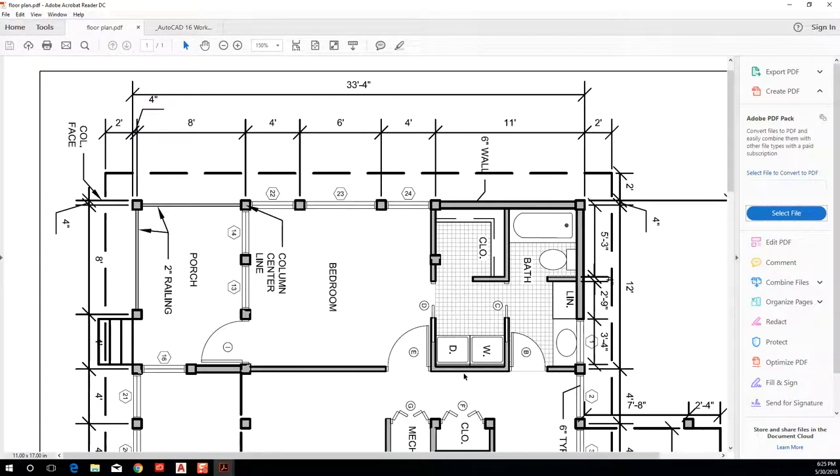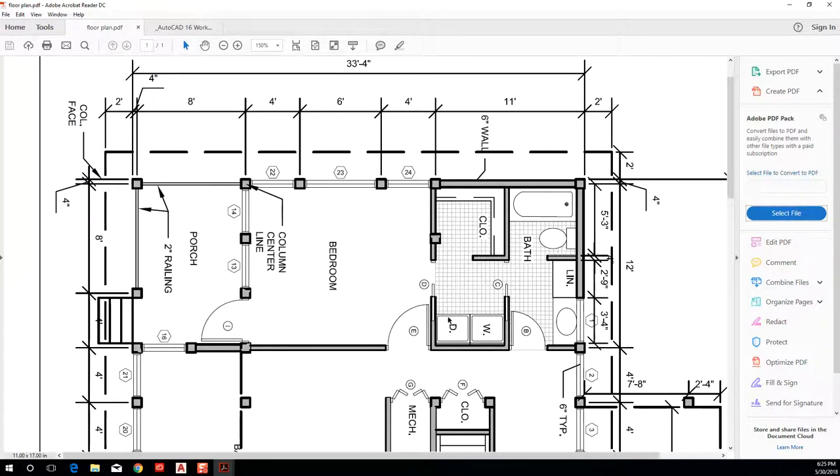This one is not quite as evident, but I would say even a grade down would be things like appliances. So we have very important architectural elements like walls and structural elements. Those are given a very high priority, and they're a thick pen weight. Then we have secondary architectural elements like doors and windows, right? They're still important, but less important than walls and structure, so they're given a medium pen weight, okay?